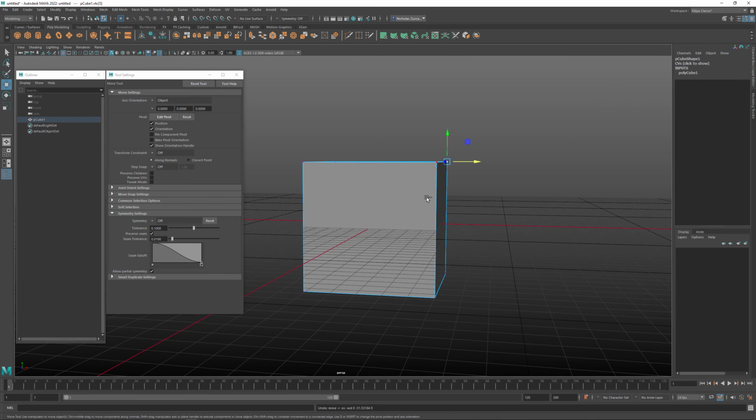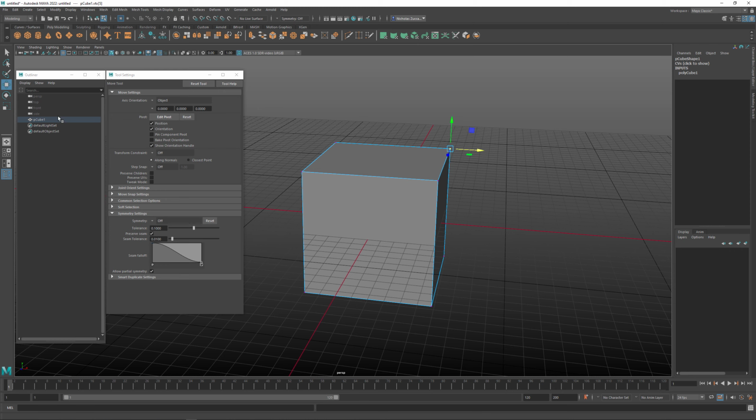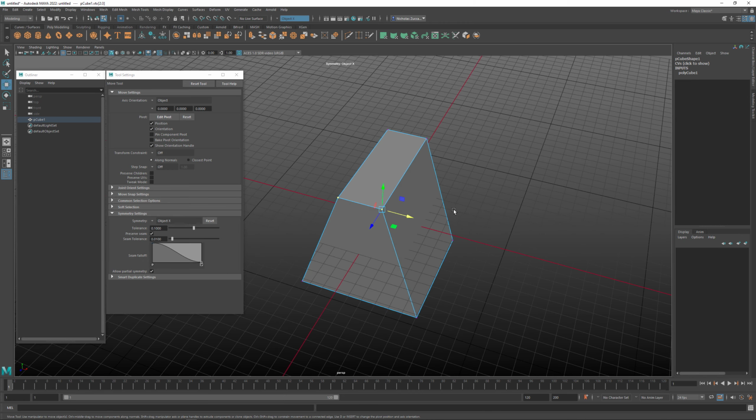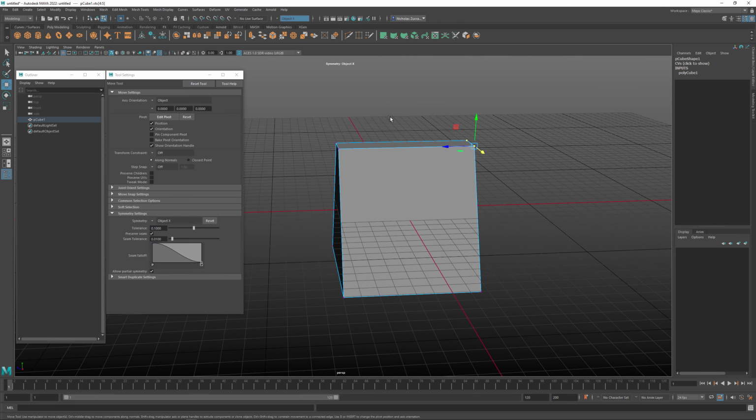And I'm going to hit undo real quick. And I'm going to turn on symmetry. We can keep it an object because everything's good right now. But we can see that we can tweak the shape, and if we want to keep everything symmetrical, this is a nice tool. And if we hold down X, we can temporarily turn on grid snapping. Now you could turn grid snapping on and leave it on constantly, but I like to use the hotkey for that. And so we could snap with this right in through here.